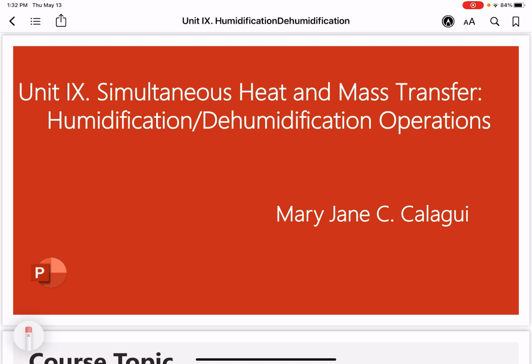In this type of operation, the gas is brought into contact with a pure liquid in which the gas is essentially insoluble. As a consequence, the liquid can evaporate because the temperature of the gas is higher than that of the stream of the liquid. The liquid can evaporate and the gas becomes saturated with respect to the liquid. Alternatively, by cooling the gas, condensation of the liquid can take place. Air conditioning processes can be determined using psychrometric charts, and some also use the Mollier diagrams.